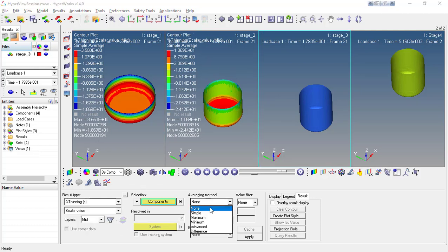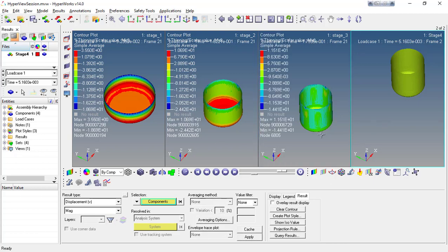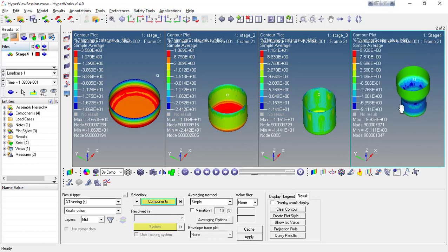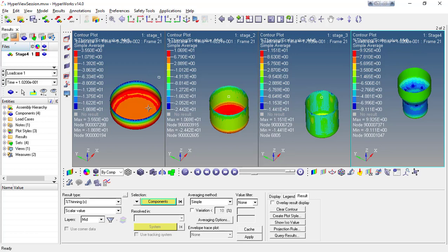Similarly for the third stage, and similarly for the fourth stage. The most important thing that you have to concentrate on is that those thinning results are not going to be added in the average step. This thinning is the individual thinning result. Here we are getting 3.5% thinning, here 10% thinning, here around 11% thinning, and here only 9.9 and 10% thinning in the individual stage. Okay, not in the combined stages.